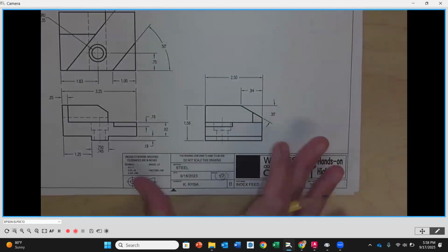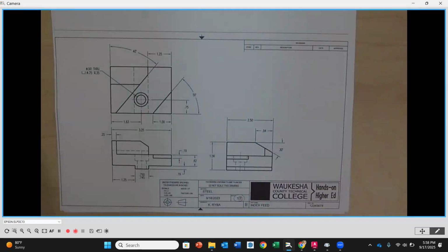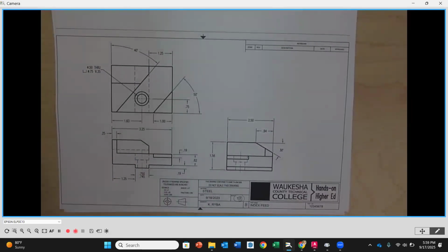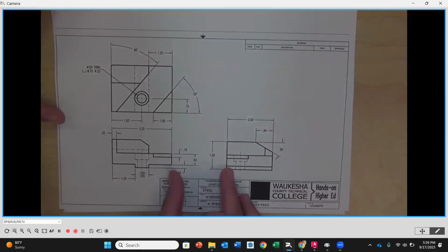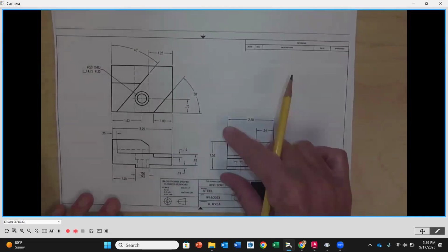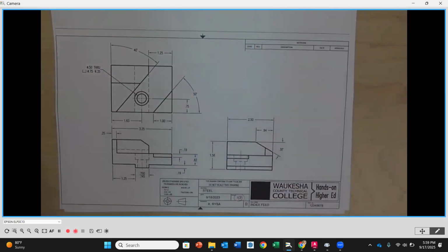All right, now, the other thing that you're going to notice is on my drawing border here, I want to kind of space things out. Number one, so that I have enough room to put my dimensions in place, but also to use up the space on the drawing. So, for instance, you'll notice that this distance, from just doing the drawing that we did, is wider than when we put the miter line in place, okay? And that's okay. Because we have CAD, we can literally move this view away to give more room to add dimensions. I don't want anything squished.